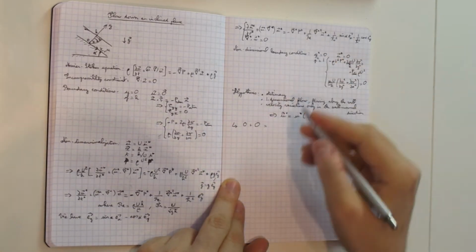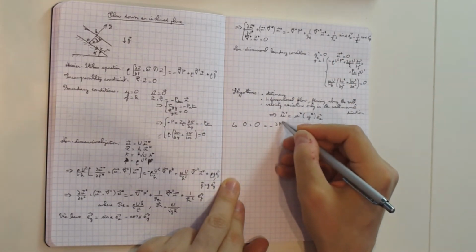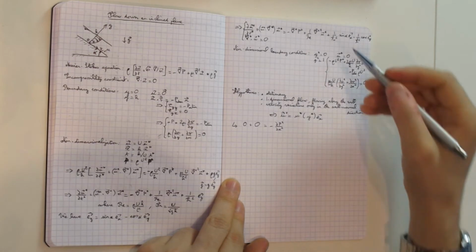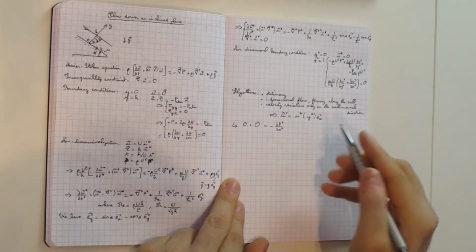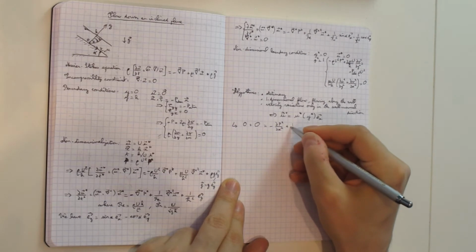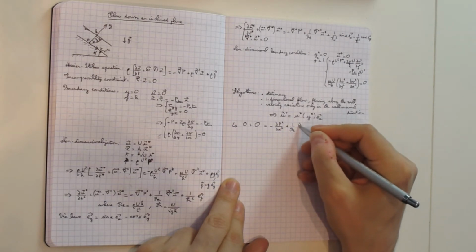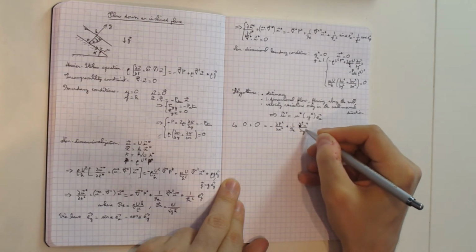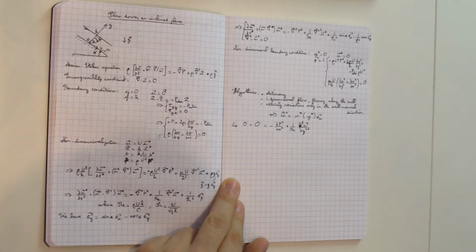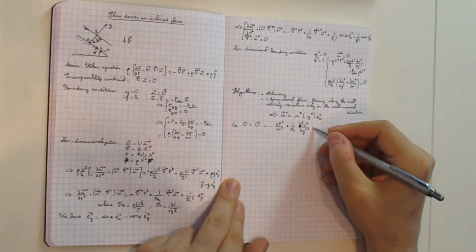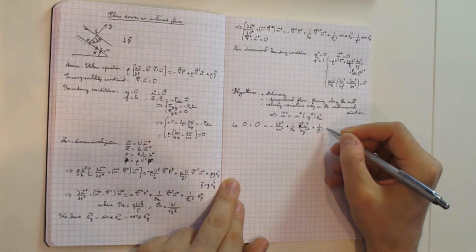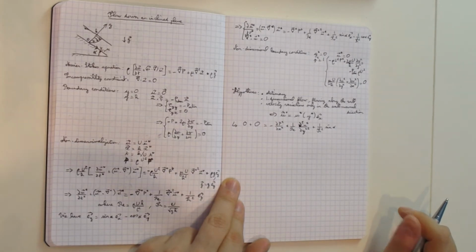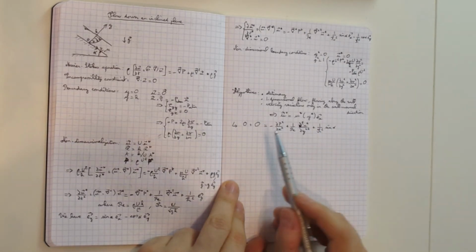Then on the right-hand side we have minus the gradient of pressure, so that's minus dp star over dx star. Then I've got my Laplacian of velocity, and the velocity only depends on y, so I will get 1 over the Reynolds number times d2 u star over dy star squared. And then in the x direction I've got this Froude plus 1 over Froude squared sine alpha. That's my first equation.